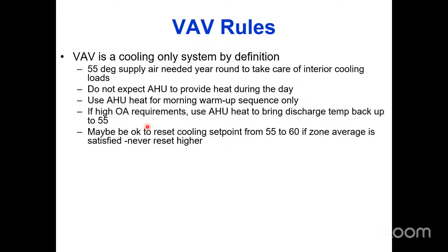So VAV, by definition, is a cooling only system. It does not heat your building. Stop trying to make the air handler run heat. It messes everything up. If you need heat in the middle of the day for all of your zones, you need a different system.